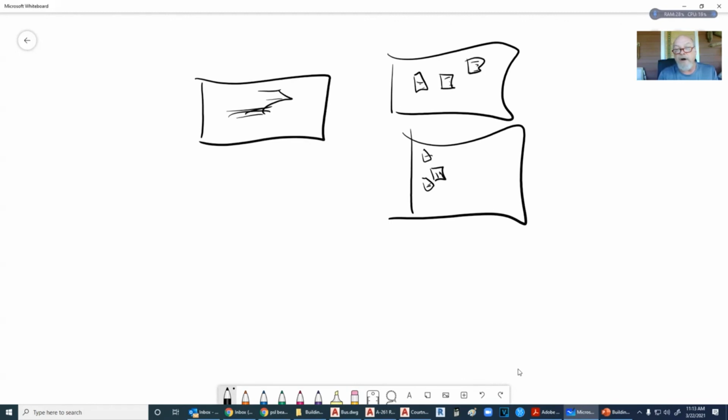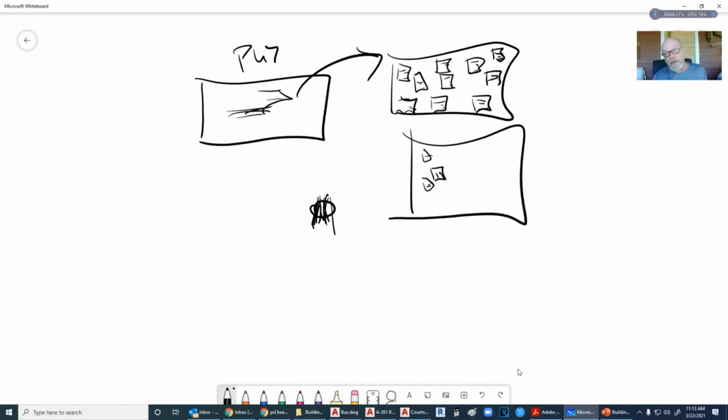So they're not going to be as strong as the LVL, but they'll be cheaper because we don't have to have whole trees or big trees to get this set up. We can take smaller trees and chip them up. There's a machine that will orient all of these chips in the same direction. And if we're using plywood, what's left over can be used as those strands as well.